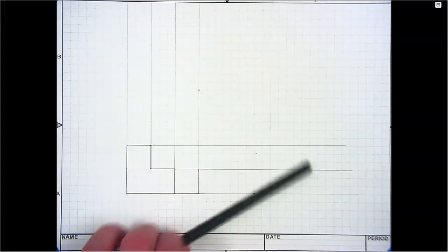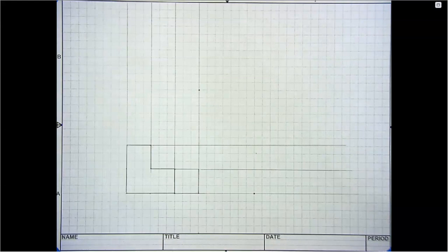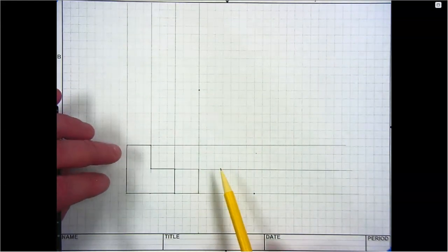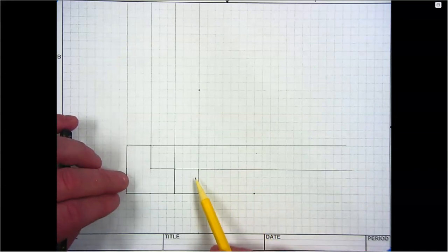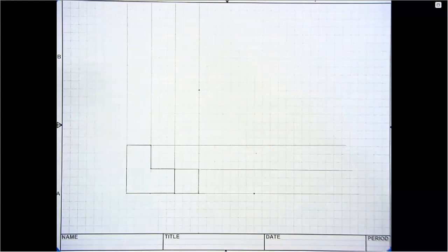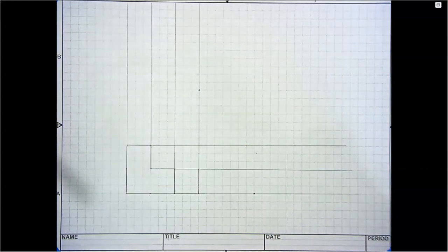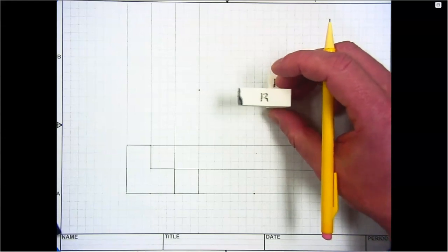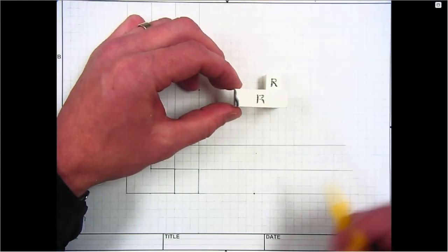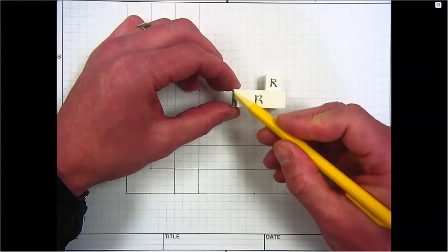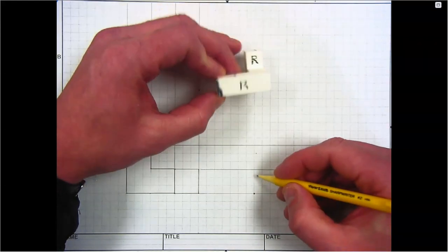So what we've done is we've created these construction lines so the features from the front view line up with the features in the right side view, and they line up with the features in the top view. And so if we look at the right side view of our part, this is the view we're going to create next. I can start at this point, which is going to be this point on my part, and I can create the line for that.